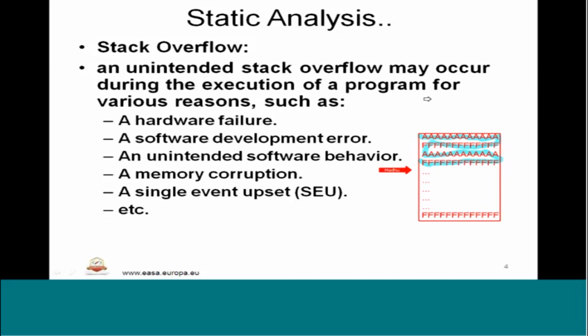Although an SEU, that is a single event upset, is unlikely to be repeated, it's going to happen a single time. If a stack corruption or an overflow occurs due to a software error, then given the same program state and input conditions, the error will be repeated. Such a repetition may cause the recovery mechanism to be ineffective. So it is very difficult to recover from such errors, which spill out of a single event upset and are followed by the overflow or the software error.